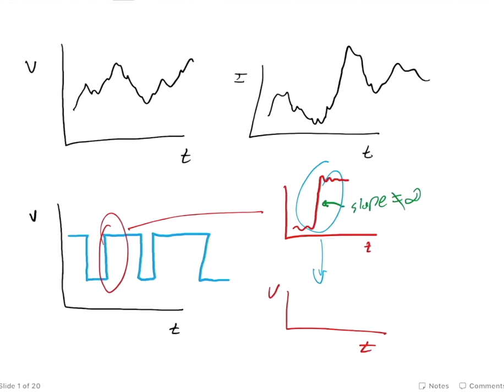If you have a digital system designed to operate at 1 megahertz, and it's being run at 1 kilohertz, you're really not going to have trouble. But if you've got a 5 gigahertz design operating at 5 gigahertz, then it's a very big deal. These sorts of rise time issues, the quality of that signal and the amount of ringing, are really at the heart of making a digital system work. The people designing ICs and things like that, it's not unusual for them to have to worry about analog sorts of issues.